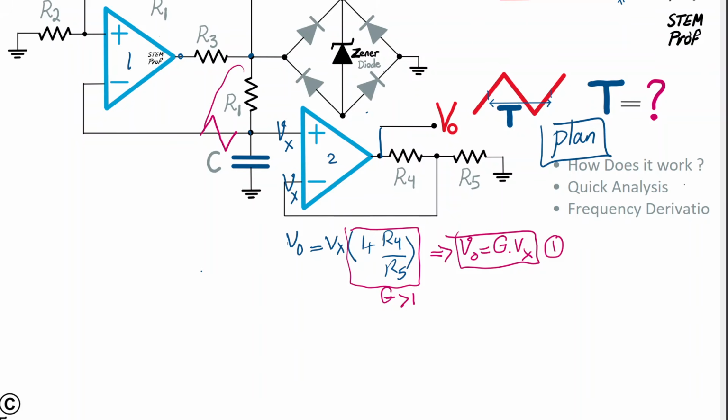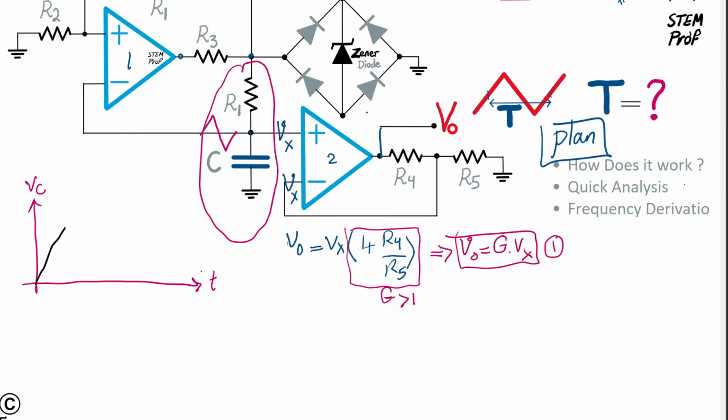Well, we have an RC circuit here. And that RC circuit is actually charging up the capacitor in an exponential manner. So we know the way that the voltage of the cap is charging up as a function of time is not linear. It is actually, let me just show you here, in an exponential fashion like this, getting to the final value if we let it charge up.